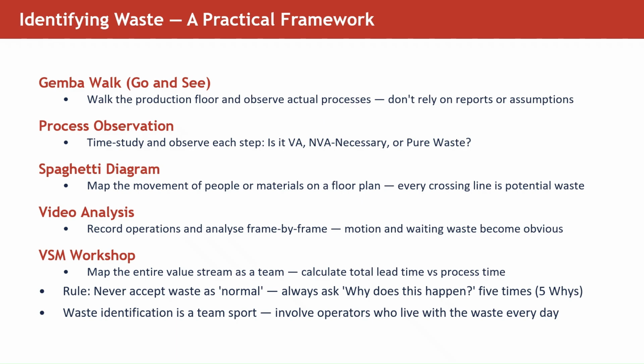So during a Gemba walk, you do four things. Observe silently without interfering. Ask questions of operators, not their supervisors. Take notes and photos, and resist the urge to jump to a solution. Do not come to a conclusion directly. Take out the process observations, observe each step. Is it a pure waste?